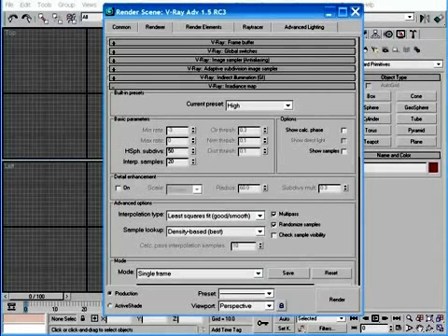And what makes the algorithms behind the irradiance map so great is they approximate GI more accurately in areas that require more detail, such as shadow transitions in places where different surfaces interact. And they are applied less accurately in places where detail is not needed, and this is usually in flat, open areas.